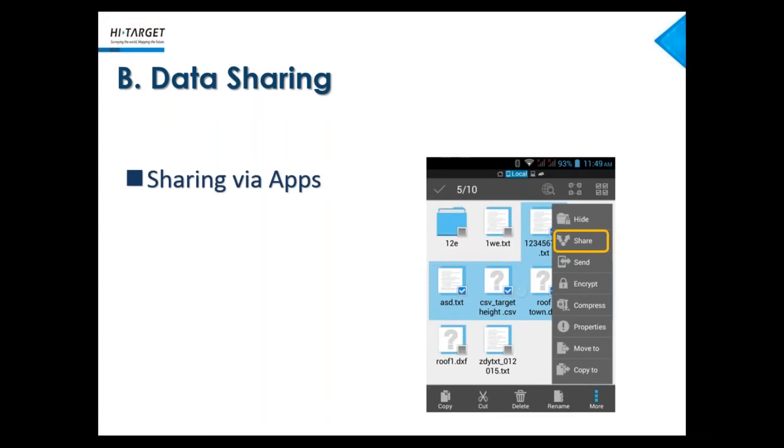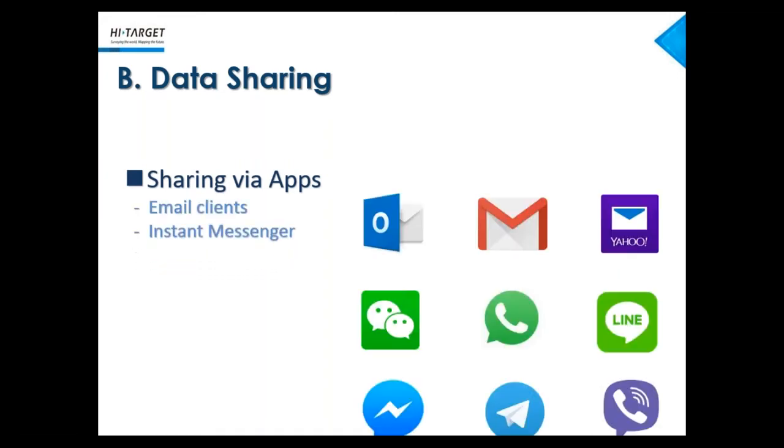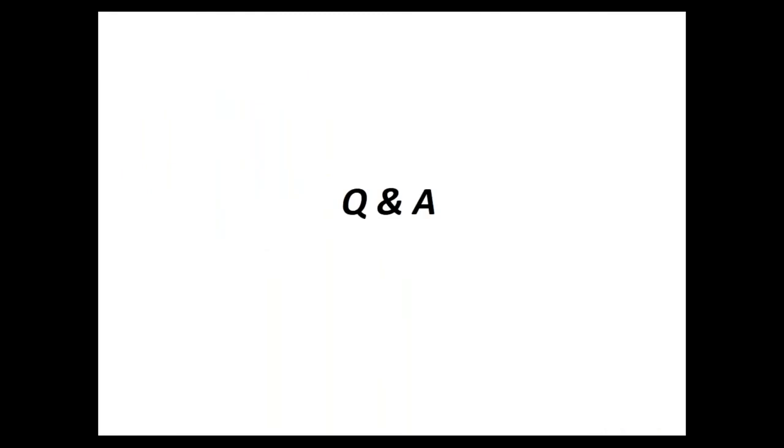Okay, that is not my main question. My main question is how to set out 3D polylines. When I'm staking out 3D polylines, it doesn't give me the height that I should go down or up. It just states the difference of height between the start station and the setting out point. Do you have a solution for that?